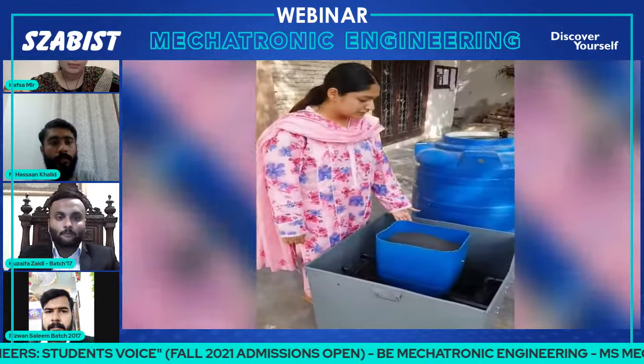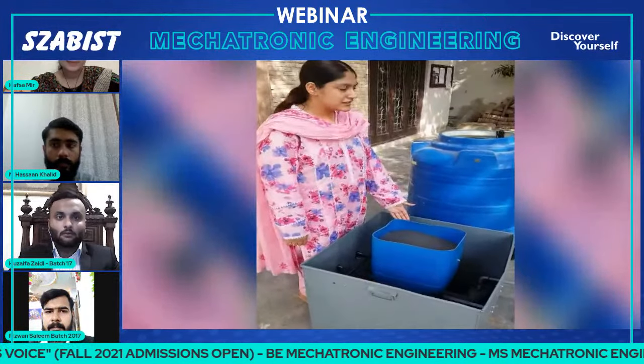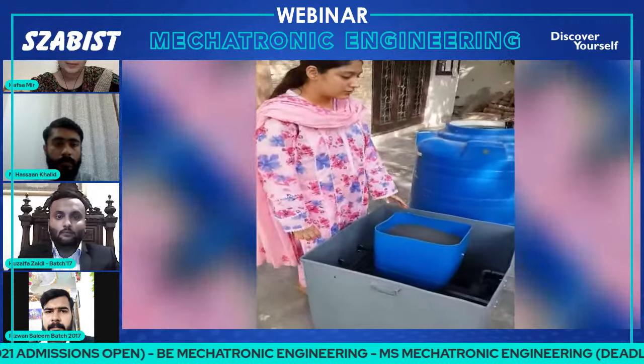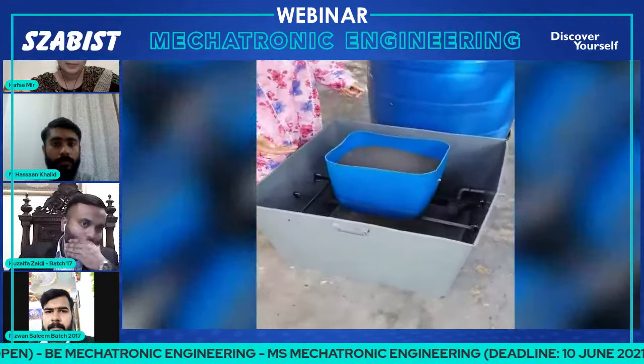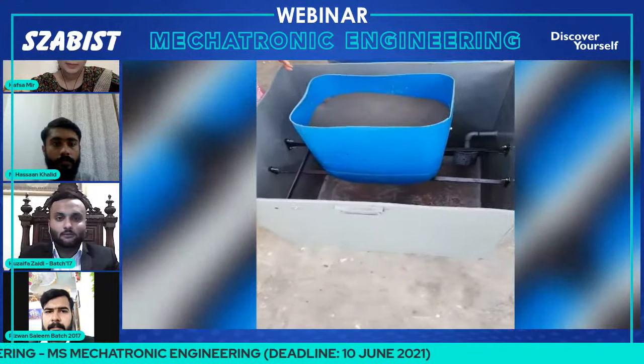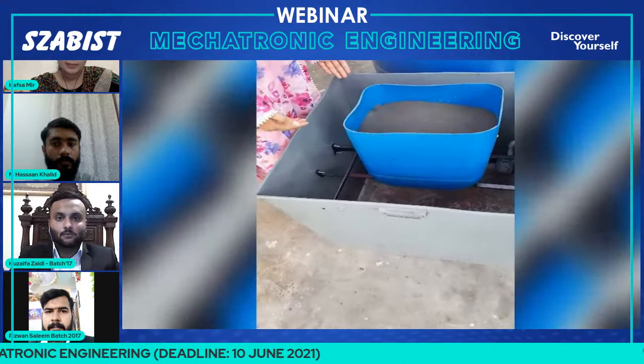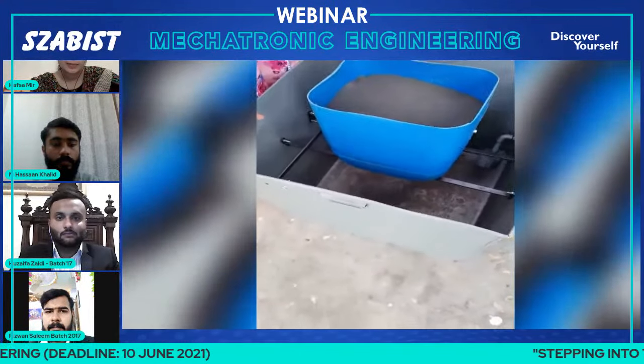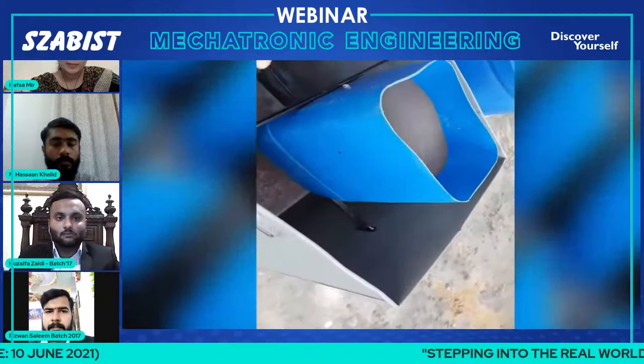So the lower layer is a polystyrene layer that will clear the water out and give a shine to the water. This is a biofilter that contains bioballs. This is used to filter out the ammonia in the water through nitrification.